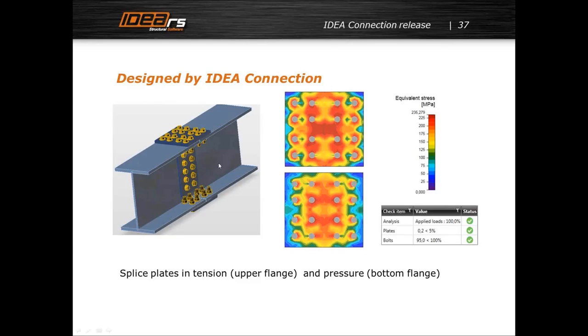There is the bending moment. The top plate is in tension, the bottom plate is in pressure, and you can see where the bolts are working. This is in tension, this is in pressure, and so the stresses in the plates are different.